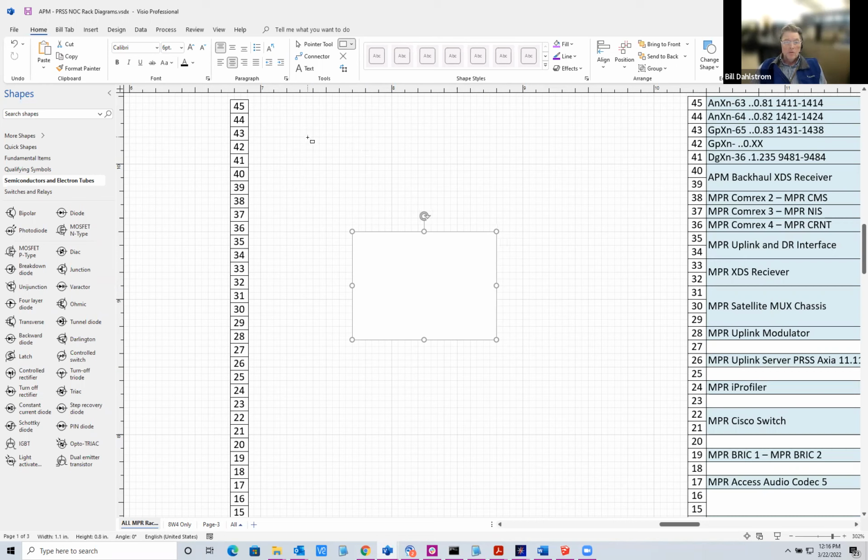The other thing is glue. Shapes will want to glue together. If I have two of these boxes and I take another one, they will glue together edge to edge, which is really helpful for building things. You can turn off glue and snap, but when you've got a grid up and some glue and some snap, you can make things line up and go together really nicely, which is a great tool, but you do have complete control over that.